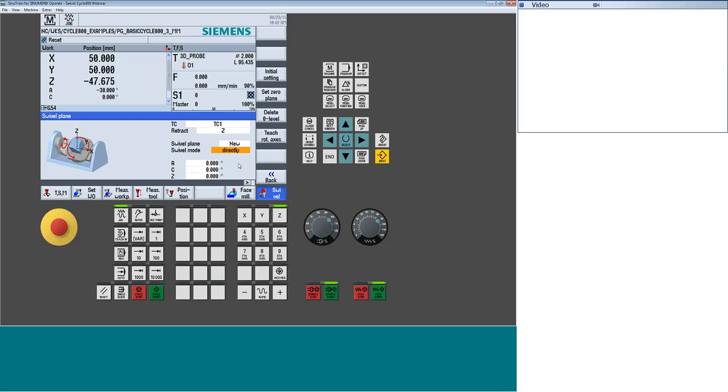You'll start to find yourself using axis by axis from the part programming scenario because it's a little easier when I have compounded rotations. I don't have to think about, well, what does the rotary have to do, like let's say in this machine, if I wanted to tip my system 45 degrees in the A, that's easy. But what if I needed to tip it 45 degrees in the B?